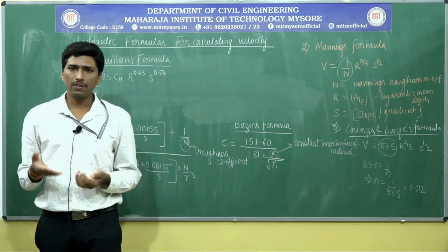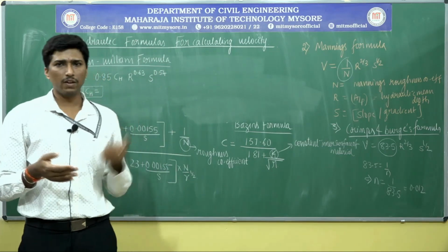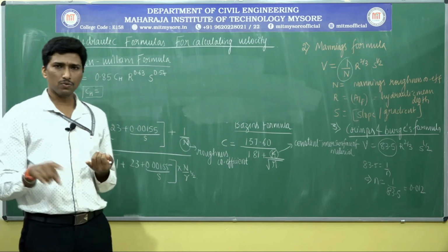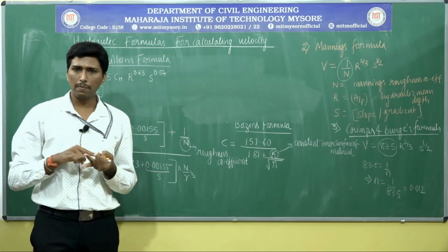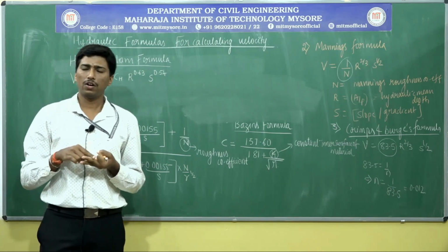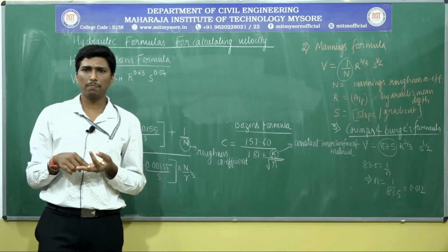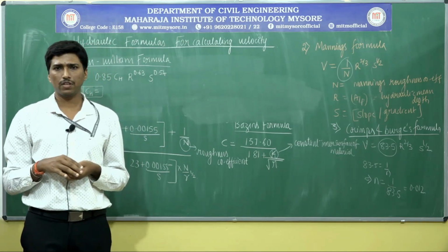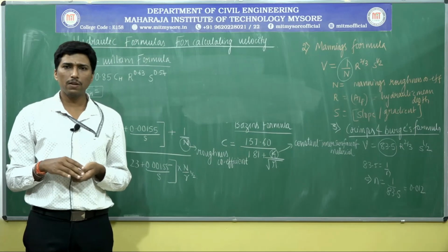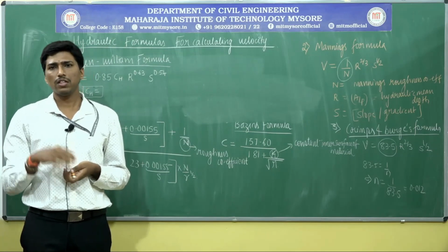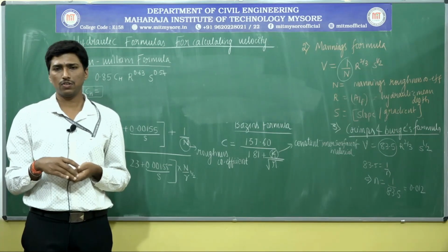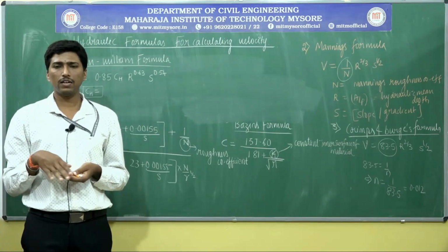So it is different, like 120 or 130 for that, and so on for different asbestos cement pipes, RCC, cast iron pipes, plastic pipes; everything will be different in nature. The roughness will be major in the case of concrete and others, but the wear and tear is also more.